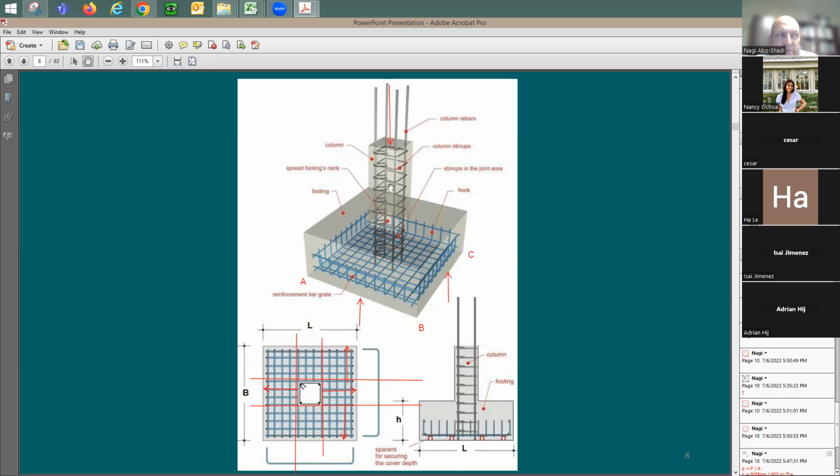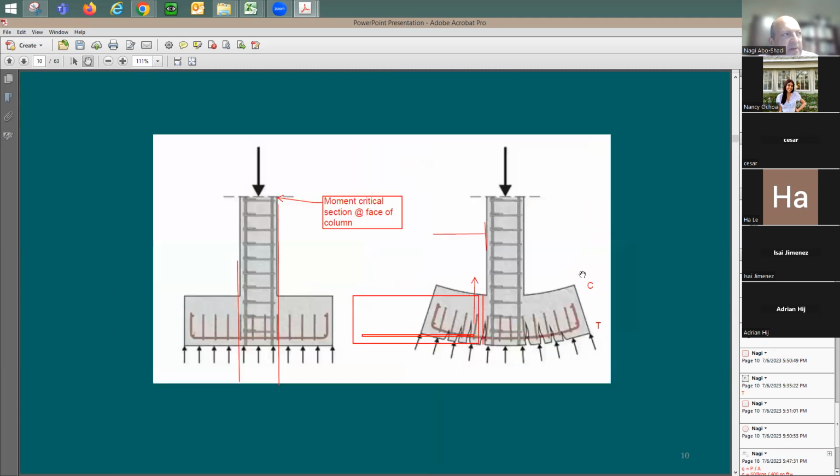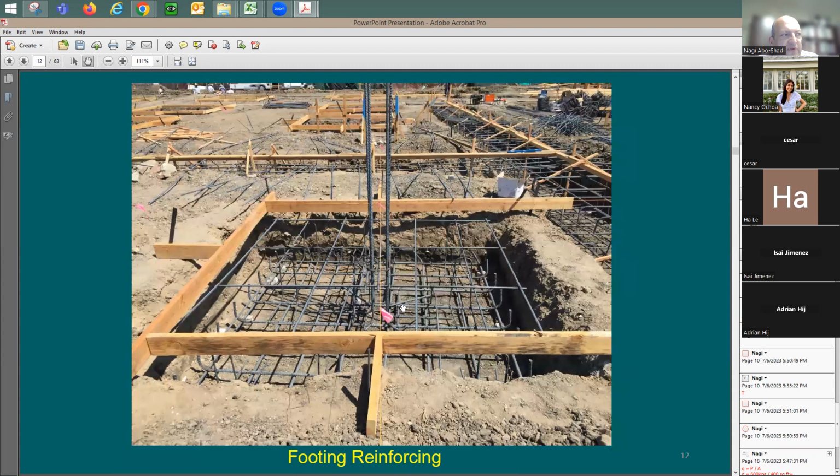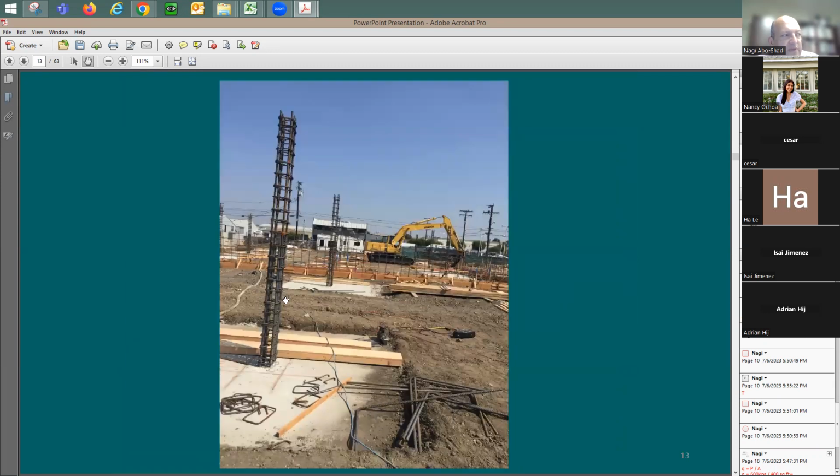So the column is round because most likely the architect would like to see it, right? It's like an artificial feature. But how about the footing? Footing is going to be just buried. Let's look here. You see, the footing is going to be below the soil. So here I may have a round column, but down below, no one's going to see it. So why should I go with round? Because the round footing is going to be more expensive. Does it make sense?